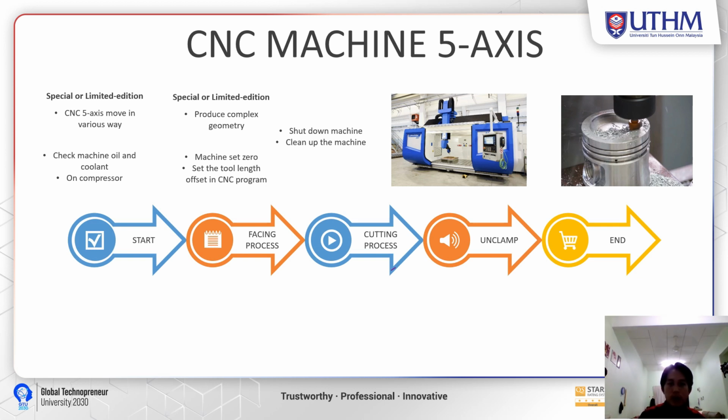Next, the ring groove on the workpiece was cut and cutting tool number 3 was pushed away from the workpiece to perform the boring process. Finally, take the workpiece and the tool out of the spindle. Next, users must clean up after themselves and properly shut down the machine to keep the work area clean and leave the machine and tools in the location and condition specified.